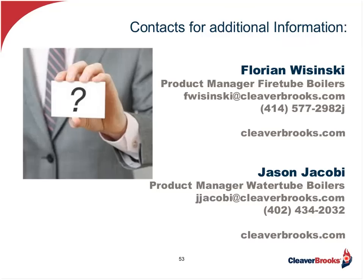There are designs to accommodate that, and certainly something one should look at if you've got a high degree of makeup and you want to try to take advantage of absorbing some of that latent energy that's just going out the stack, and put it into your feed water, whether you're firing oil or gas.